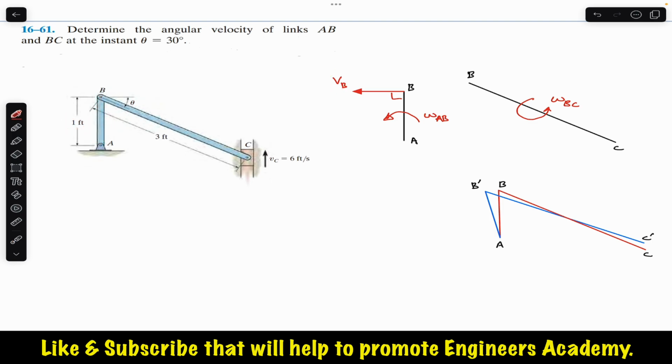So the magnitude of VB will be the radius of the circle about which point B is moving, multiplied by this omega. This will be 1 foot times omega AB, so that will be omega AB. So the VB magnitude is actually omega AB. And similarly, we will have that same VB here at point B, since this represents link BC. So this is that VB.